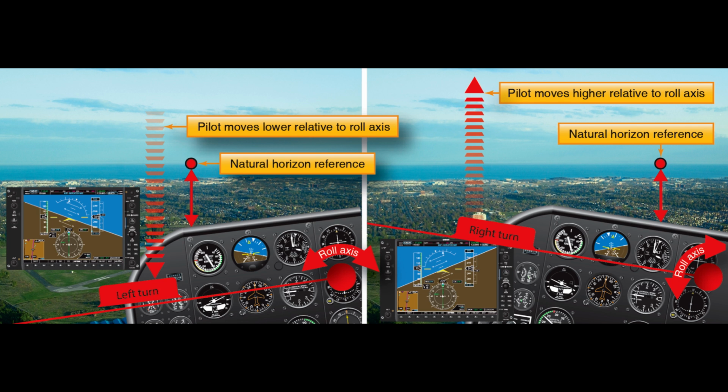If trim was used, such as during a steep turn, forward elevator pressure may be required until the trim can be adjusted. As the rollout is being completed, attention should be given to outside visual references, as well as the flight instruments to determine that the wings are being leveled and the turn stopped.